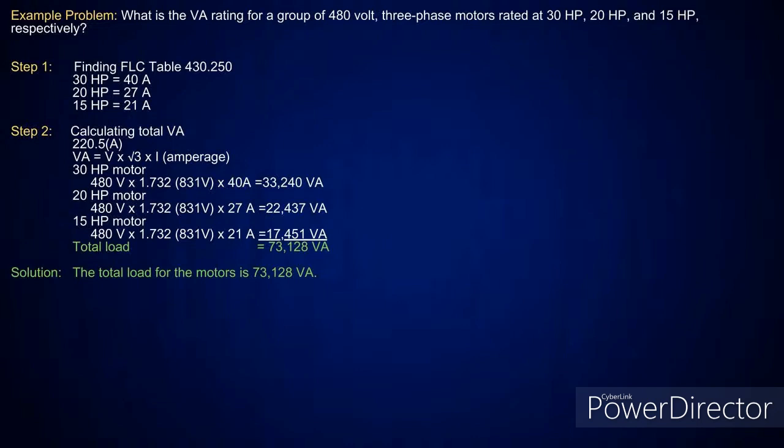Hey, I have a question about that. Let's just say you decide that you don't have 3-phase for the 21 amp motor, and you decide to power it with 480 volt single phase. Let's say it's a 15 horsepower motor. We decide we're gonna put that one on a 30 horsepower drive and power it with 480 volt single phase.